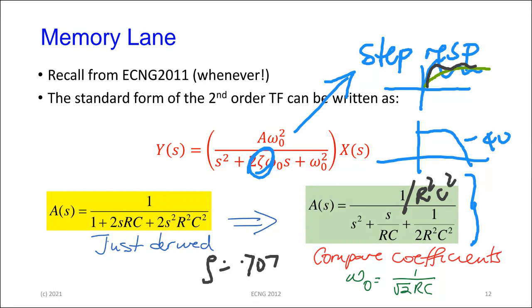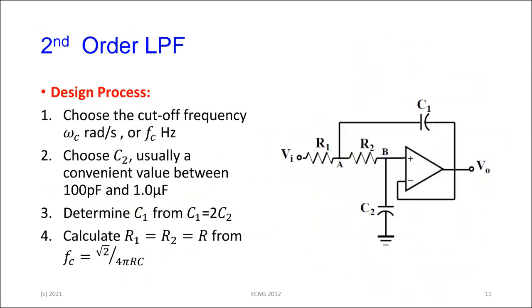Okay, why is that important? Well, just to clarify and to connect two things together, what we're doing is designing a filter. We've designed a filter, and the filter is a circuit like this. So I could get the R's, the C's, and the op amp and put it in. The op amp has a plus VCC and a minus VCC here, or you could operate it single-ended, however you want.